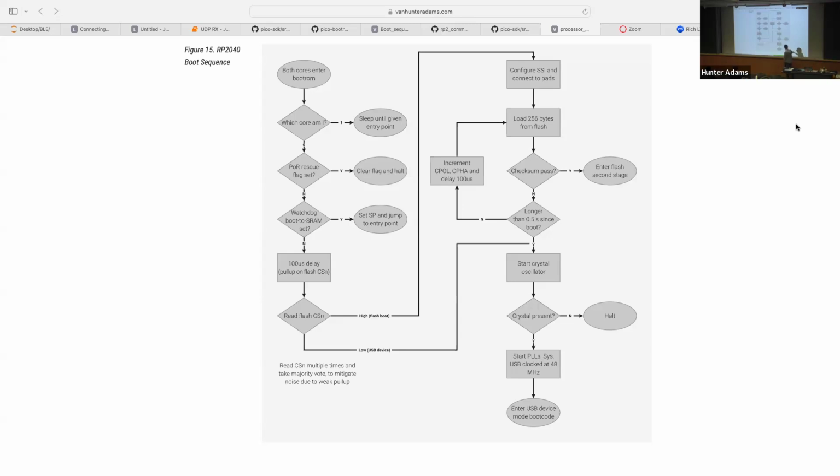So this is why, just by the way, if any of you have asked me for a new RP2040 and I got you one out of the box, fresh from the store, there is no program on there. You may have noticed, if you were paying particularly close attention, that when you just plugged that in, without even holding the boot select button, it went automatically to USB boot mode. The reason that it did that is it went through this process. It found that there did not exist a valid program there, and so it just went straight into boot select mode.